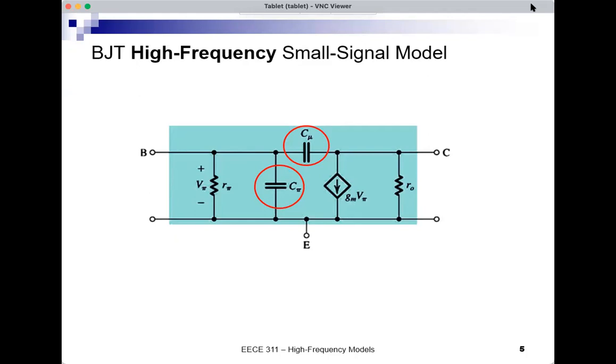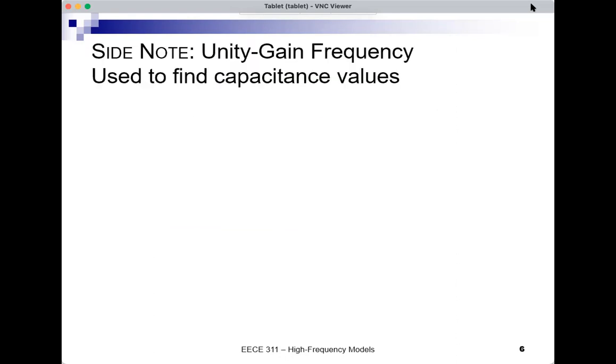They're very small, very tiny. At low frequency, close to DC, you can safely ignore them and remove them. But if I'm doing a frequency response study, they're there, they would affect my amplifier, and I have to study how they would affect the amplifier.